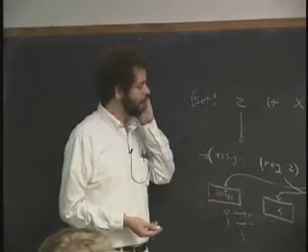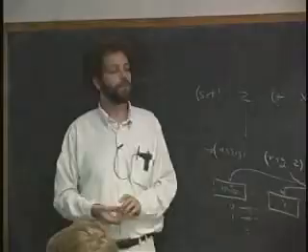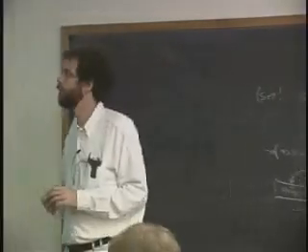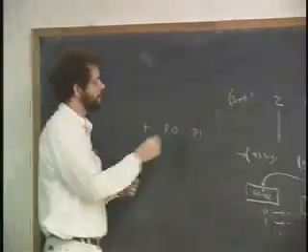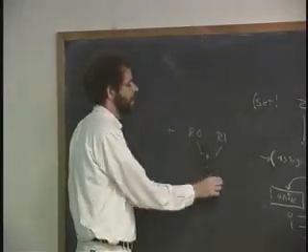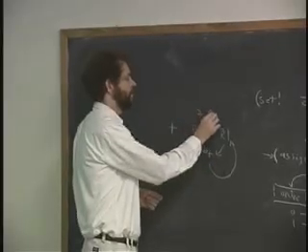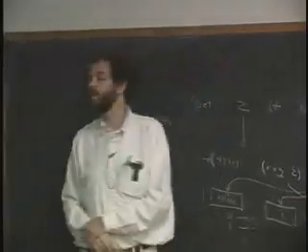But one might imagine not having one source, another source, and a destination in each one of these opcodes, but rather having fewer things and having some implicit way where some of the sources and destinations came from. One example would be: you say plus R0, R1, and what that really means is take R0 and R1, add them together, and put the result back into R1. Okay? And these are called 2-address machines instead of 3, because here we have 3 different addresses of a register. Machines like the PDP-11, back in the days when I went to school, were like that.